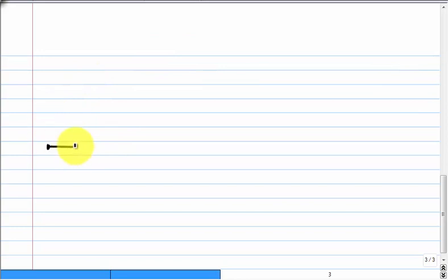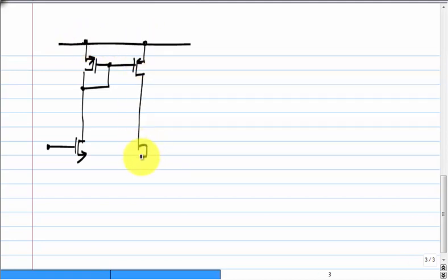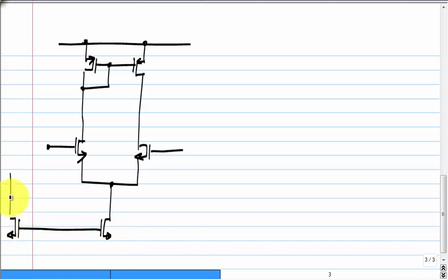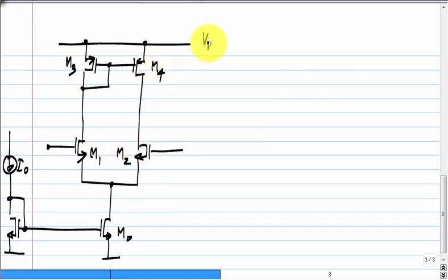So, first let's go back to the single stage op amp. Now, if everything is perfectly matched, this voltage will be the same as that and all transistors will be in saturation, but there is zero chance of that happening. The slightest mismatch will drive it out of saturation, but that is also not very relevant, because we would not use an op amp like this.